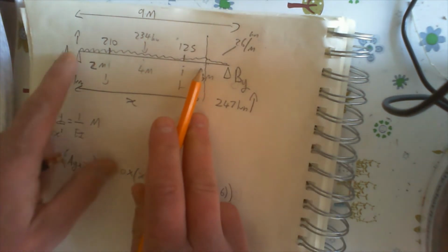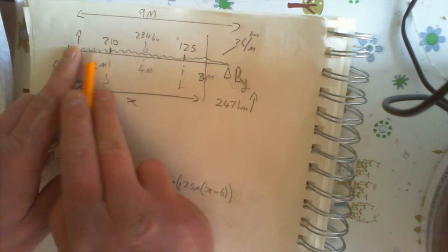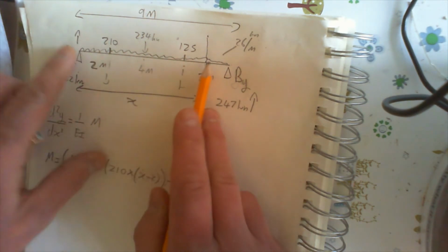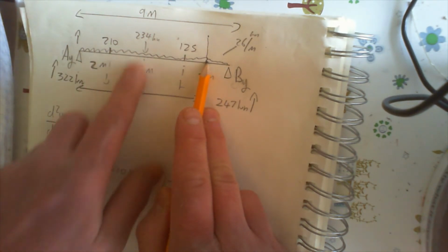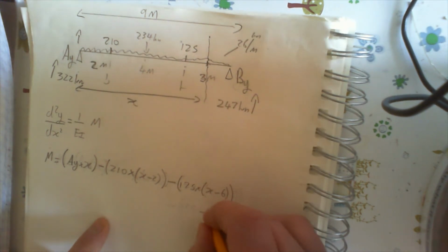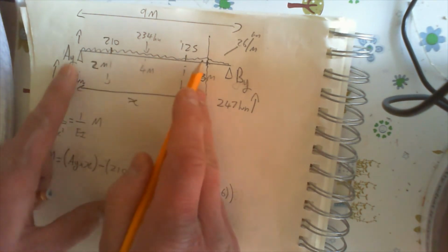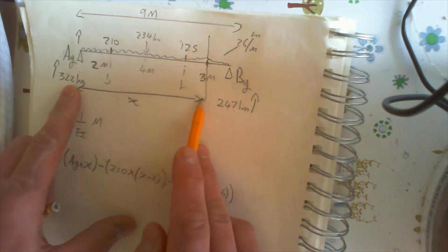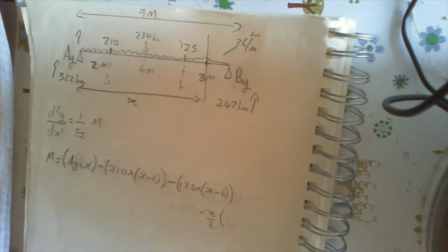Now, this bit's a bit more tricky, as we're trying to find the midpoint with the UDL, and it's only the midpoint, it's not from 9 metres, it's from this point, it's the middle of x. So the actual distance here is x over 2, because we're halfway, because remember our UDL, you treat it as a point load halfway along. So this x, halfway along, that's going to be x over 2. Now we're going to have to multiply that. Now how do we do that then?